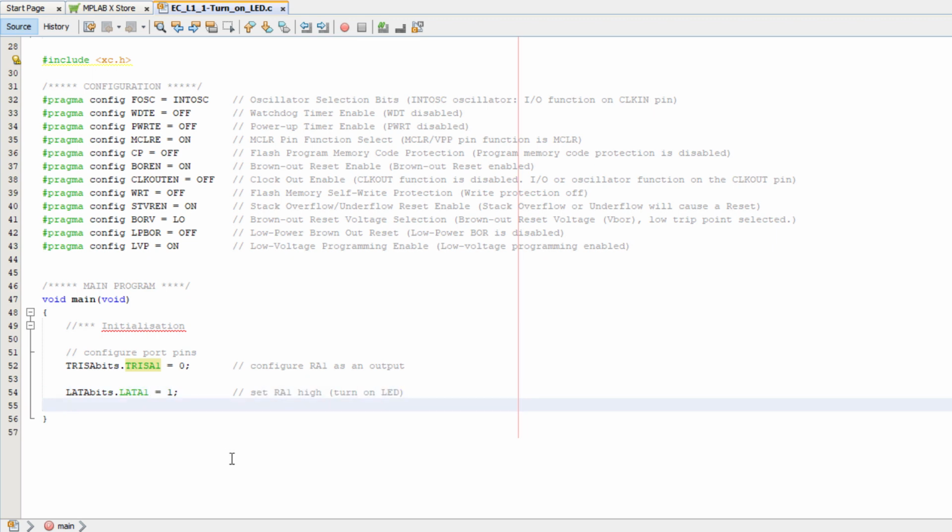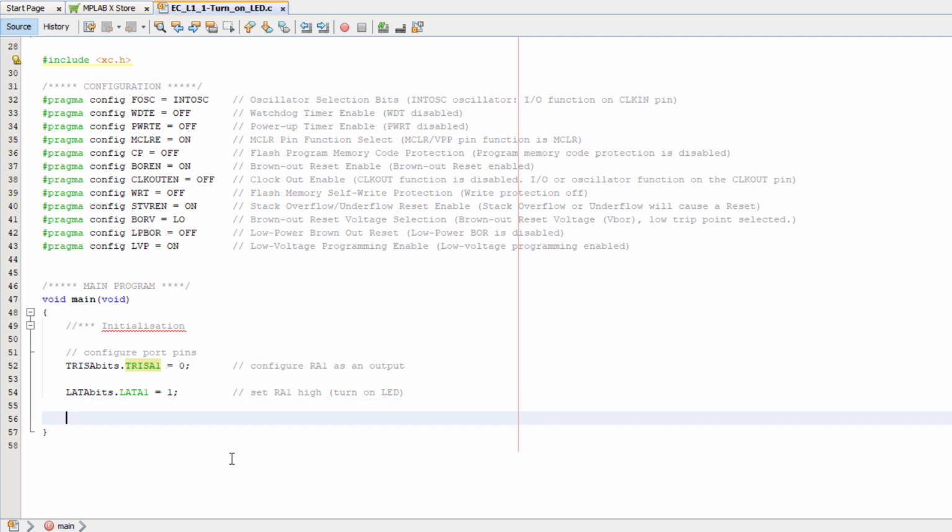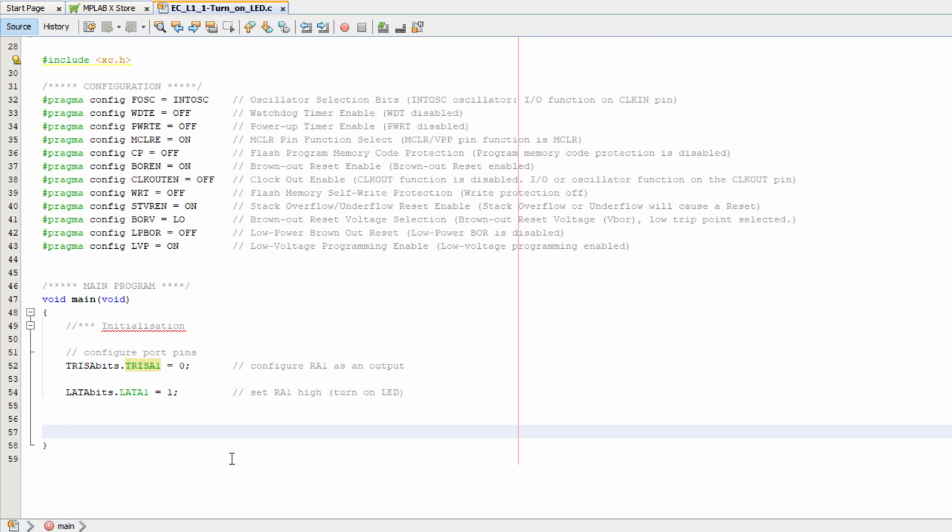Finally, remember how I said there's no operating system for the main function to return to? In a bare metal system like this, microcontroller programs usually never finish. Sure, they might shut the hardware down when they're done, but even then they usually just go into a dormant state and wake up to bring the system back to life. The program never actually finishes as such. So we need some code that will just keep running forever.